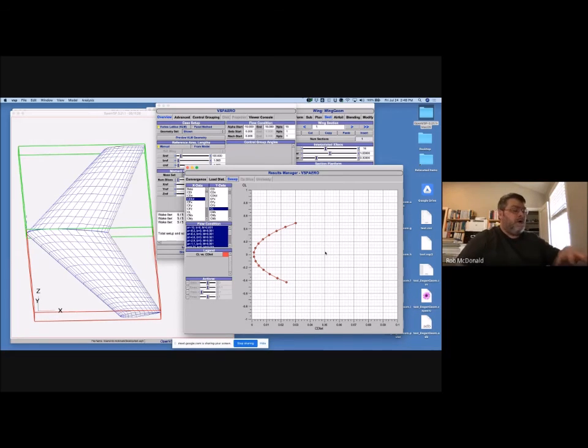So now we're not patrolling. We're not going and looking for other traps. We're not trying to cover as many traps as we can. So our metric is no longer miles per charge of battery. Now, in this moment, we just want to know: how long can we circle? And it's all about time. When you're observing a single location, your metric is typically going to be how many hours per battery. Whereas if you want to patrol a coastline or do a grid search, then it's how many miles per battery.